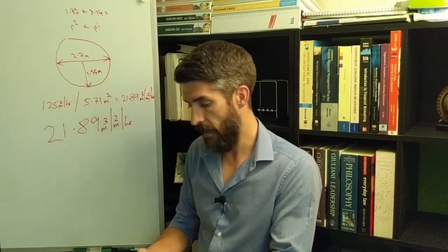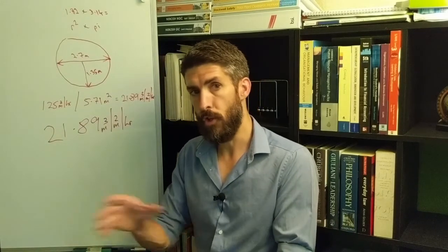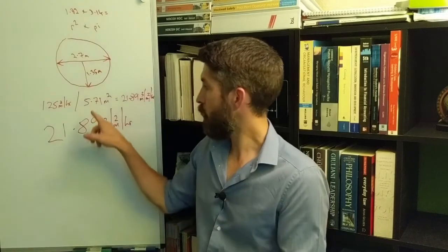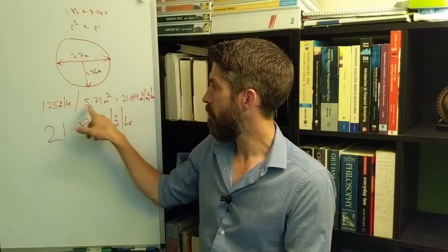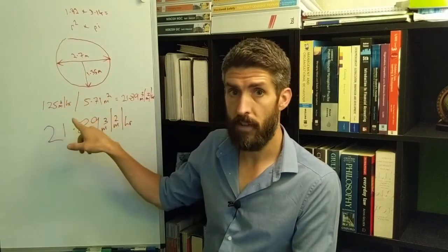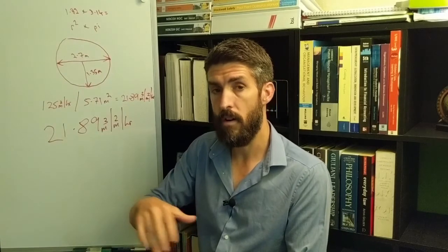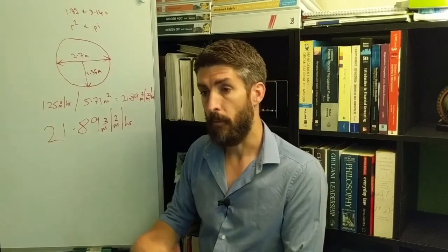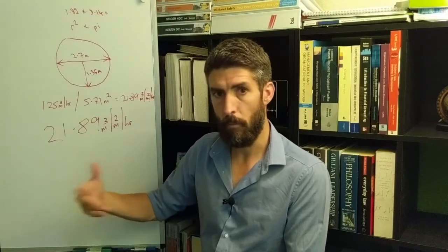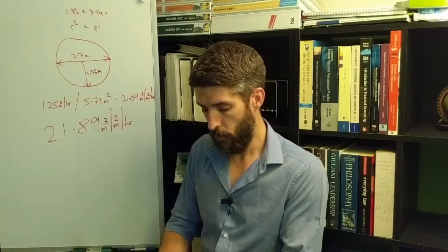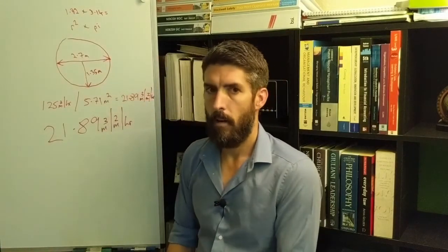You'd have a surface area of 11.42 once you take into account both filters. So you would divide the flow rate by the total surface area of all your filters, not just the surface area of one. Of course, if you've only got one filter, then that one filter comprises 100% of your filtration surface area. I hope that's relatively clear.